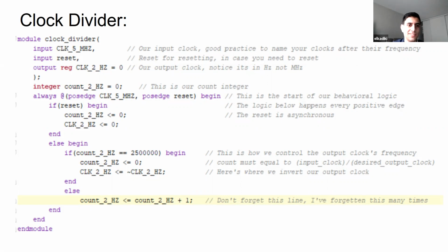When you're actually making a circuit, though, not an FPGA design, you'll want to always have it set up so you hit your reset at the start. I think this is just an FPGA problem. Because when you power on any device that's a circuit, you can't guarantee that your, say, finite state machines inside will be in a state that you want them to be in, so you need a way to set them.